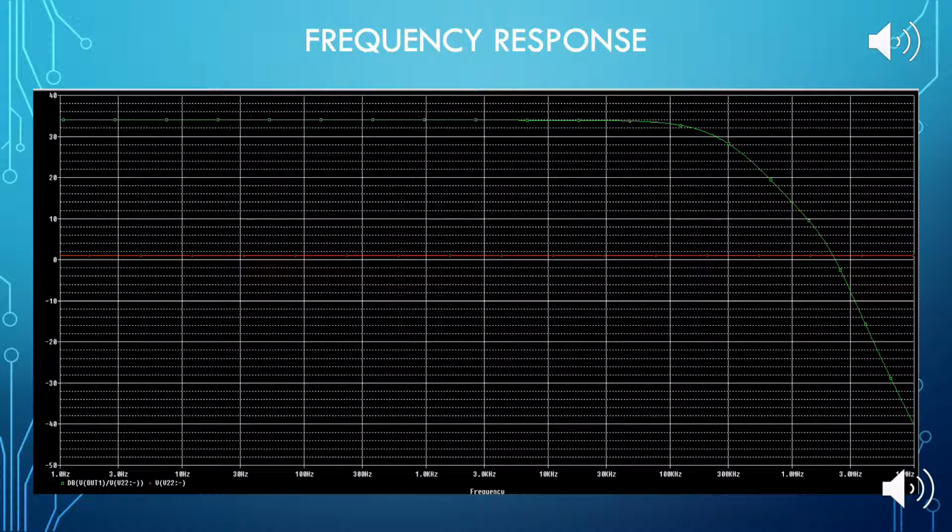And here my output bias stage is listed with my current and voltages after running the simulation. When I first started the output bias stage, I had issues at nodes P base and N base, which then affected the output stage. But after doing some tests and figuring out where my issues lay, which were wiring issues or node issues, I was able to get the currents to be around what was listed in the textbook after changing the area of my transistors to the correct area listed within the reference table.